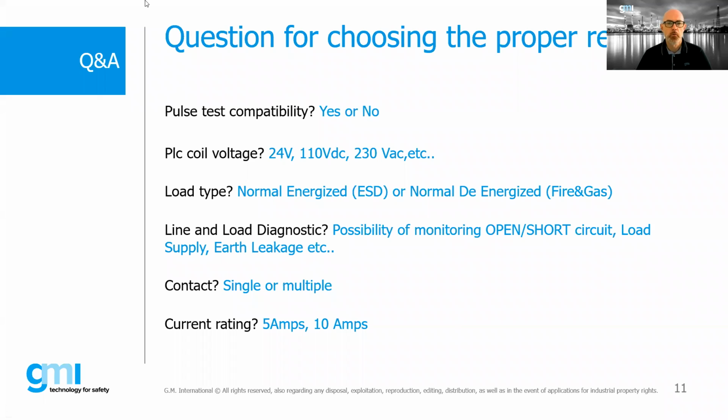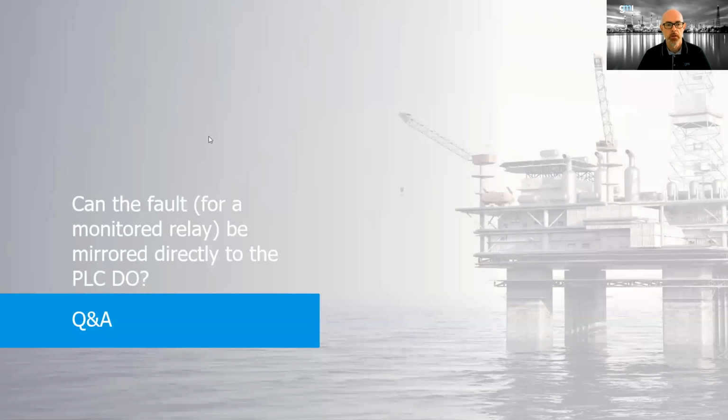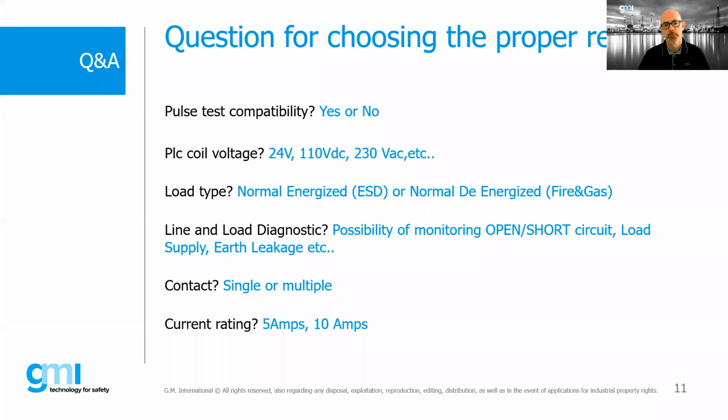This would greatly increase the risk for our system, as using a wrong relay in its safety function increases the chances of failure in case of a relay intervention request. Therefore, it's important to choose the relay correctly based on the safety function it will have to perform.